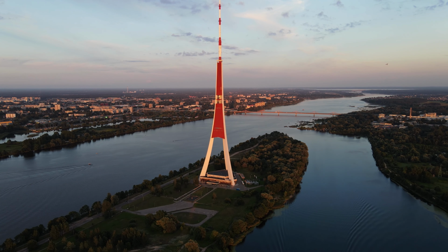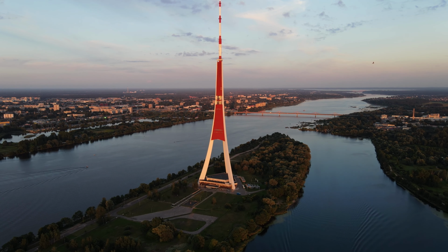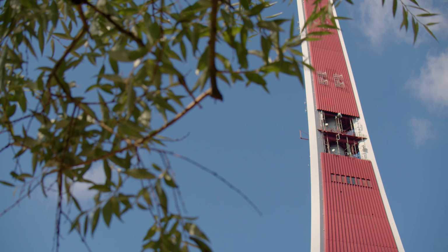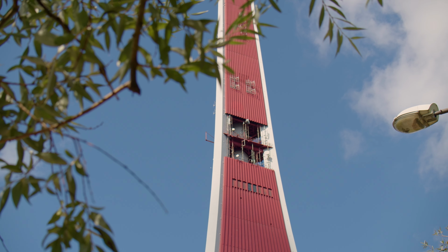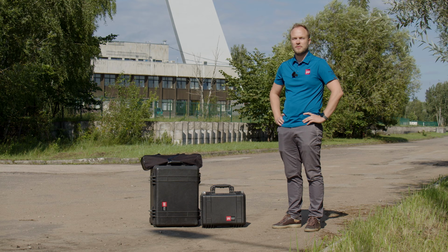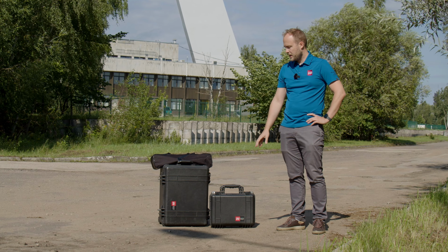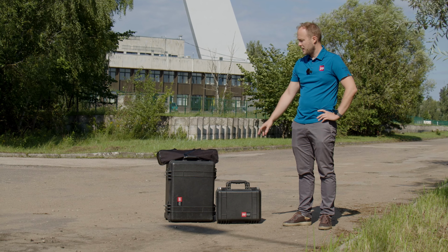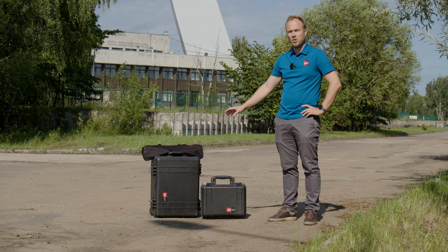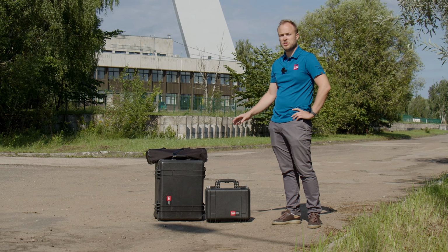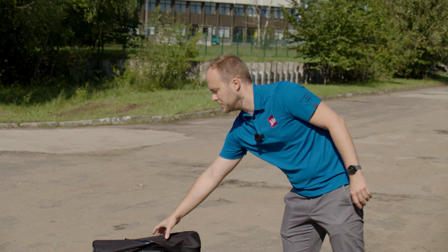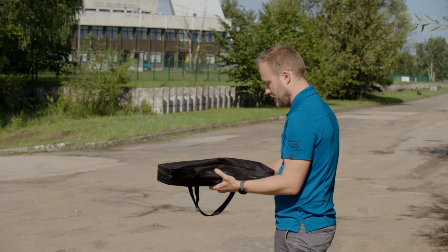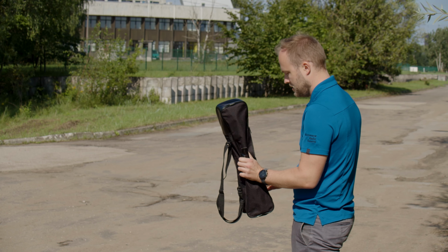And we are here today near this communication tower to do the verification for the point-to-point microwave link from the ground level. We will be using today a set of Spectrum Compact and a dedicated horn antenna to do the measurements from the ground level for this radio link. Okay, so we will start our setup with unpacking and setting up the tripod.